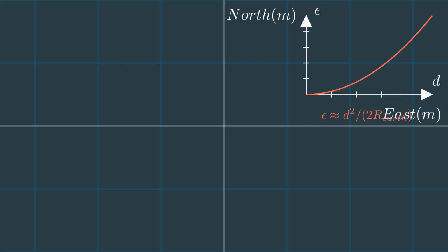How big is this error we're talking about? Is it like meters off or just tiny amounts? For relatively small areas, close to the center point V, the error is usually quite small. The documentation suggests typically less than 0.2 meters, so maybe 8 inches or so, for distances under 50 meters away from that center point. Okay, 50 meters, like half a city block, maybe? Yeah. Less than a foot of error sounds pretty acceptable for estimating parking. For many applications, it is.